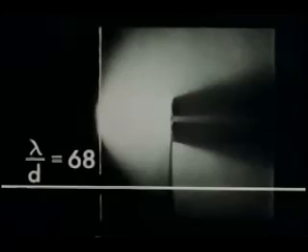The purpose of the hole in the washer is to show what happens to the incoming molecules as they encounter the molecules scattered back from the model. The hole is so small, it has very little effect on the distribution of molecules in the backscattered cloud. We see that in free molecular flow, the cloud of backscattered molecules is easily penetrated, and the molecules approaching from upstream pass right through the hole to form a molecular beam behind the model.